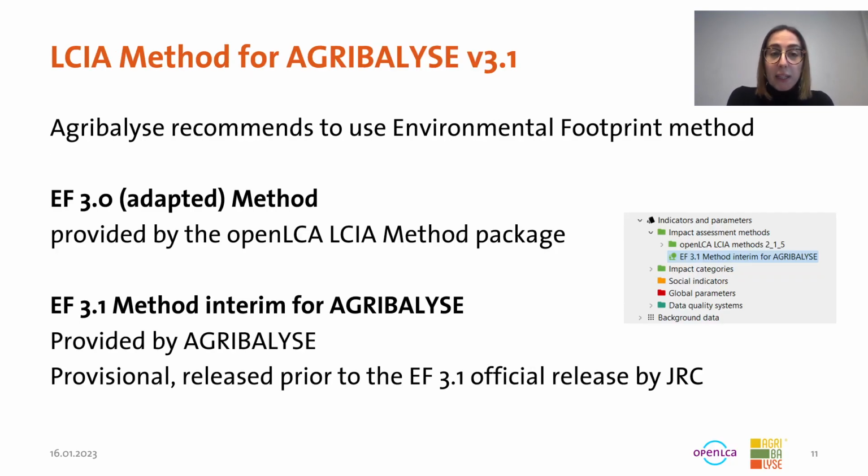Then AGRIBALYSE recommends to use the environmental footprint method for their database. The method package of openLCA already has the EF 3.0 adapted method, which you can download, which is already present in the database under openLCA LCIA methods 215. And also AGRIBALYSE came with an EF 3.1 interim for AGRIBALYSE method. This was provided by AGRIBALYSE and now works with openLCA and AGRIBALYSE 3.1.